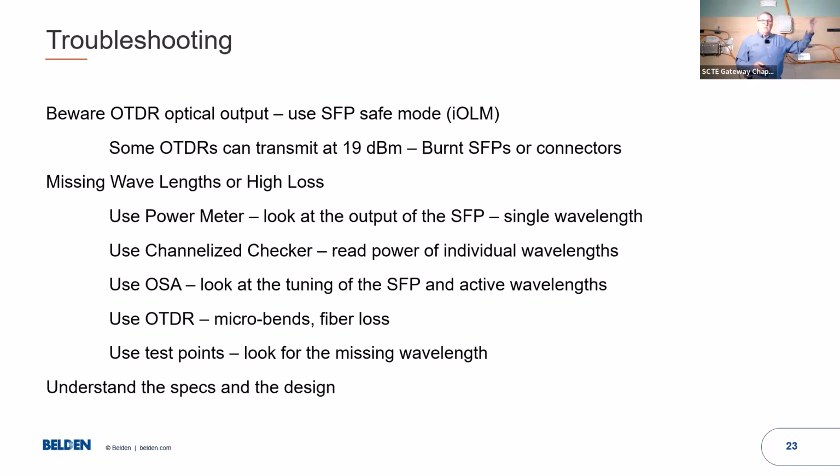Receivers in the head end used to, receivers in the field used to be set for 0 dB, right? 0 to 1, more or less, right? SFPs in the nodes now are looking for -17. They have a range of -10 to -24 or so, depending on the MSO and what you're looking for in your range. Transmitters in HFC used to put out +10.